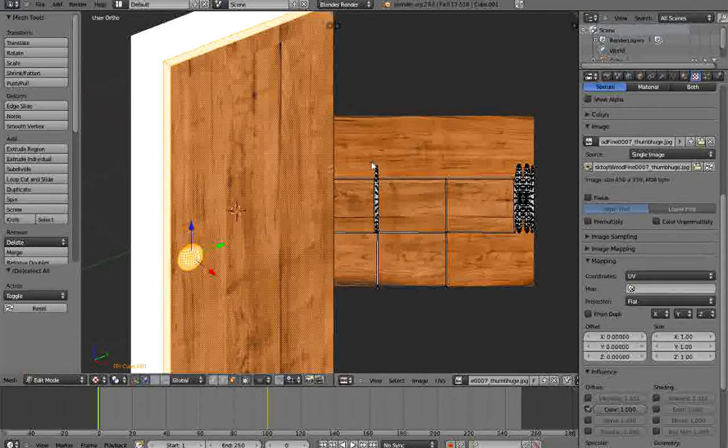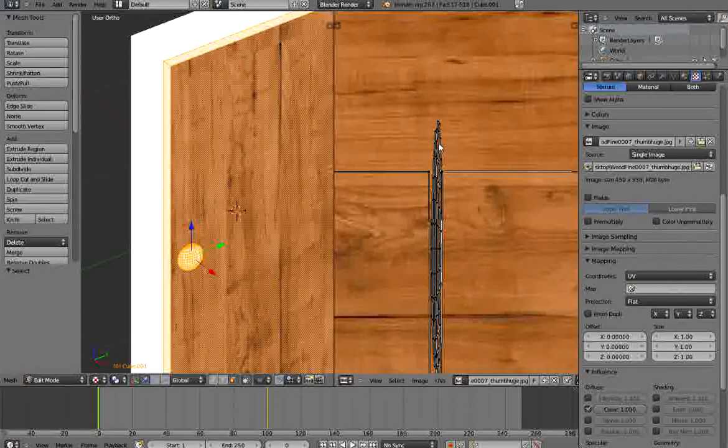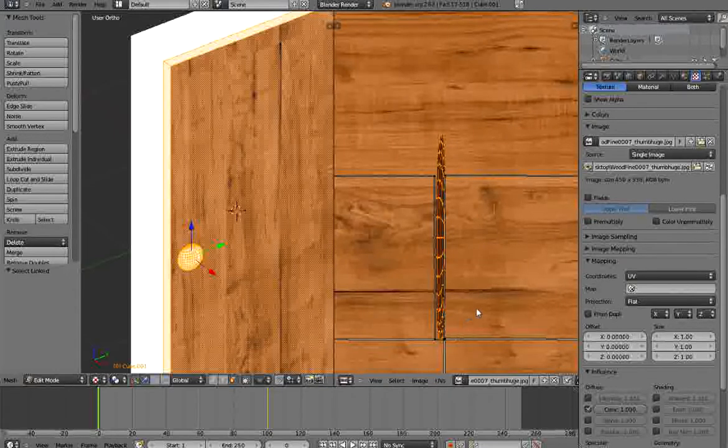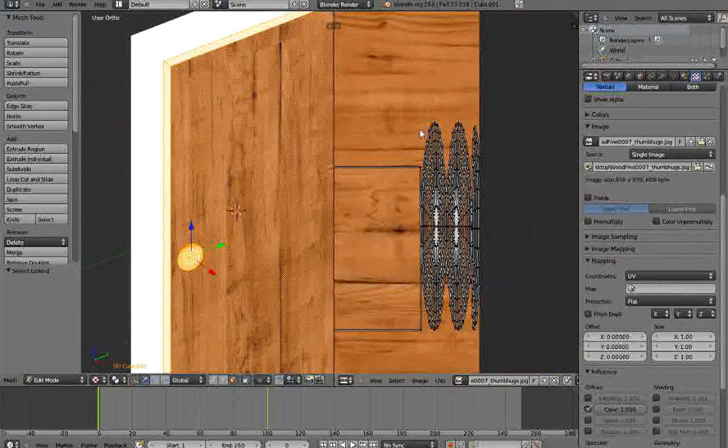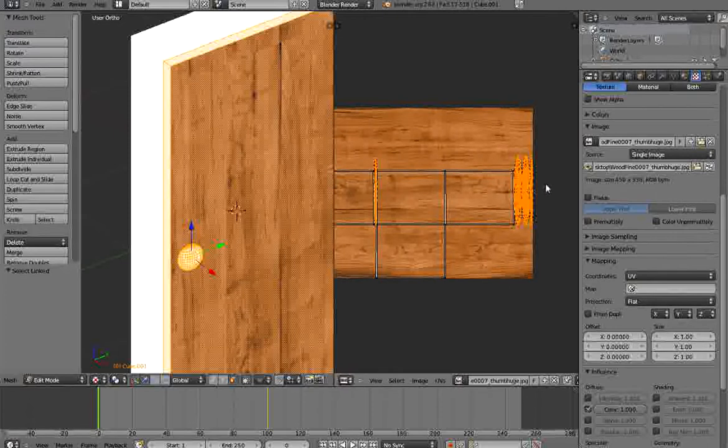So what we can do is select these spheres, and you can either select one vertex at a time, which would take so long. We don't want to do that. What we can do is just select one vertex and then hit Control-L, and that'll select all of the linked vertices. Let's go ahead and do that. So if we select one vertex on each of these spheres here on our texture map coordinates, and then hit Control-L, it'll select our spheres for us.